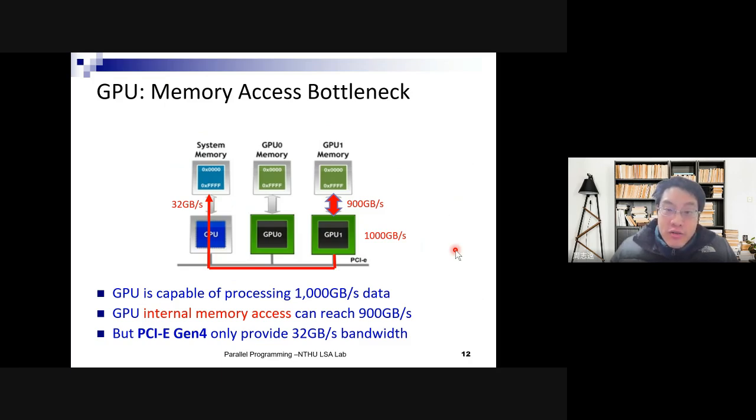For example, just like your homework three, when we taught GPU, we kept saying the real bottleneck of GPU is memory access, right? So even though you have a solution like Tensor Core, it will actually escalate the problem of memory access. It does not mitigate or reduce the problem, it actually increases it. So that's why memory access becomes an even more urgent problem we need to solve for a solution like GPU.